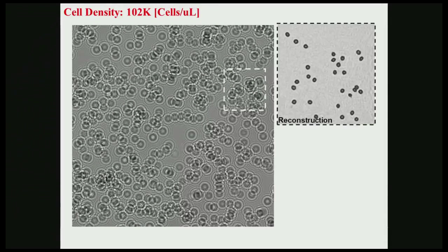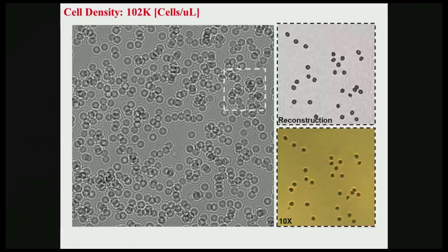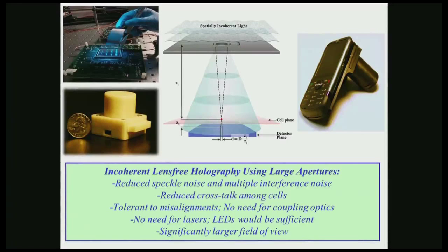a background. So basically, you start with these dummy-looking shadows, and using Fourier optics and phase retrieval algorithms, you retrieve the phase that is missing at the CMOS and reconstruct an image, as shown here, except there is no optics, there is literally no objective lens or any other imaging system between the cells, in this case blood cells, and the CMOS imager, nicely matching a traditional light microscope.